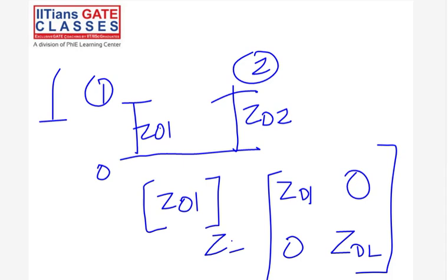Alright. So in cases like this, since there is no connection, so basically just think about this. So physical significance is that if I inject current at node 2, since there is no physical transmission line between 1 and 2, the voltage at node 1 is not affected.